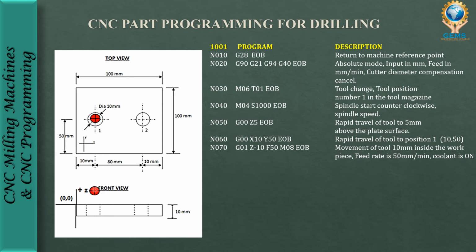Now the spindle starts, the tool will rotate and machine, and it will reach till here. You can notice. The tool will come here, or you can mention a little more, Z -20, so that the tool will move a little further down.